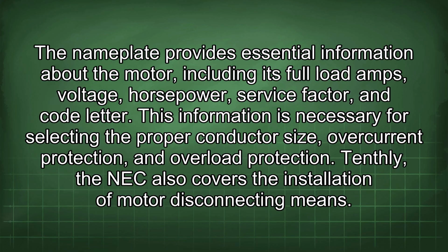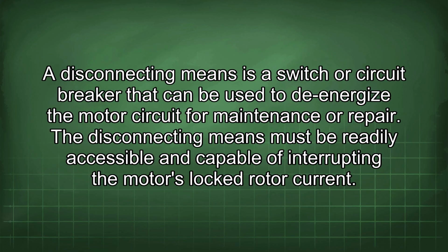Tenthly, the NEC also covers the installation of motor disconnecting means. A disconnecting means is a switch or circuit breaker that can be used to de-energize the motor circuit for maintenance or repair. The disconnecting means must be readily accessible and capable of interrupting the motor's locked rotor current.